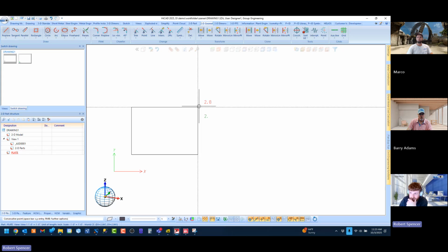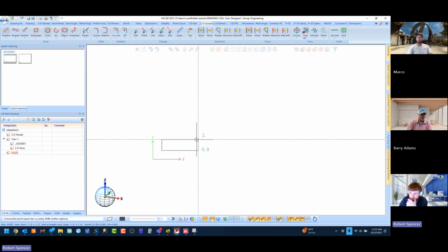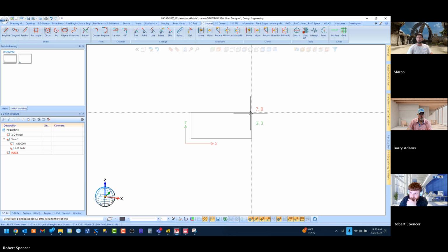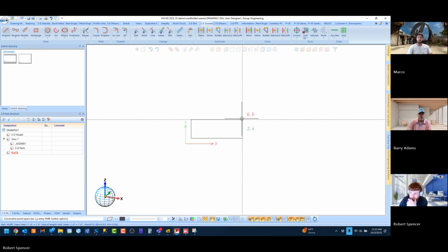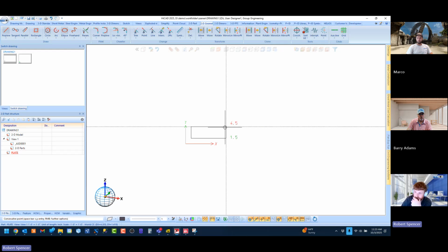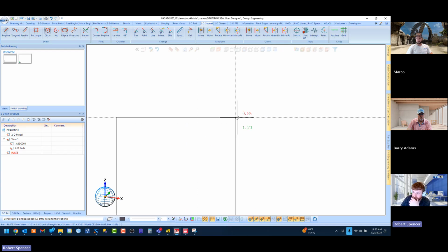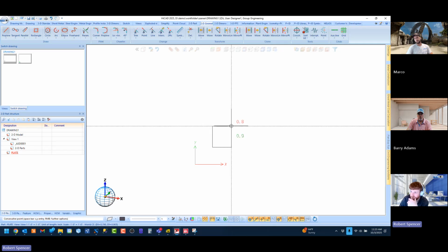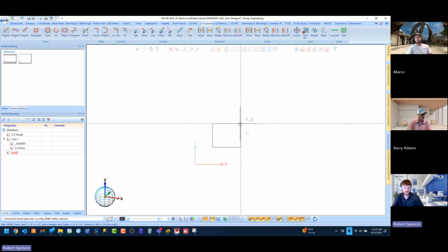And you can use the snaps there. If you zoom out, your snaps get, I guess, tighter, or they get looser. If you zoom in, you see now you got different decimal points going on. So the zoom impacts the snaps of your cursor, using that scroll wheel.